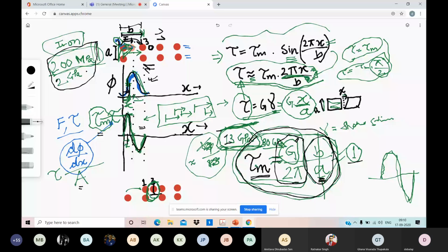Why at a much lower stress value does yielding take place? And by now you know that yielding is a small but detectable amount of plastic deformation, where as many as 10 to the power 5 to 10 to the power 6 number of dislocations move.